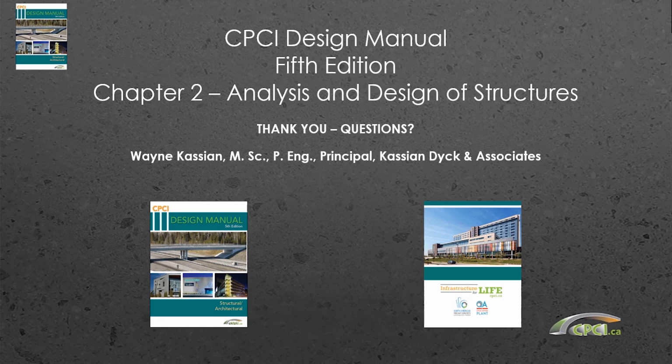So although CSA A23.3-14 and the NBC 2015 have been out a long time, these codes probably won't be used in Ontario until 2019, whereas other provinces, like the Atlantic provinces or others that don't have their own provincial code, would put them into effect when they adopt the NBC. So the timing of when these provisions are to be used is a function of the province your project is working under.